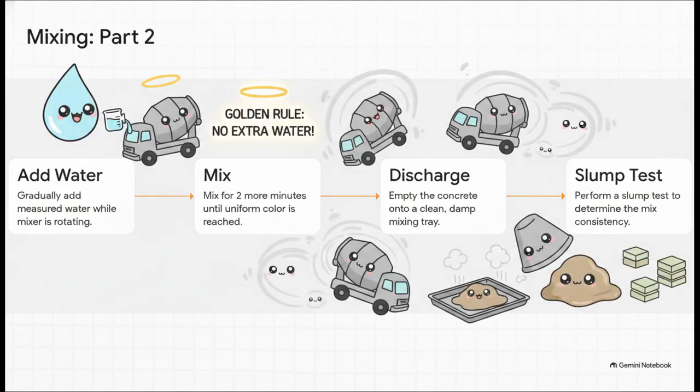Now, check out the water integration step. We gradually add the measured water while the mixer rotates. And the golden rule here? Never, ever add extra water. We let that mix for another 2 minutes.